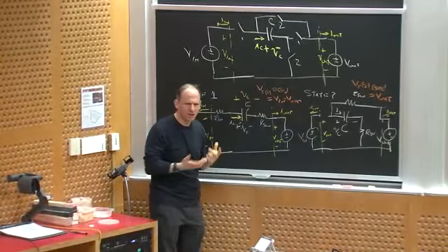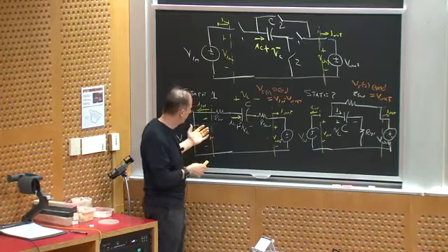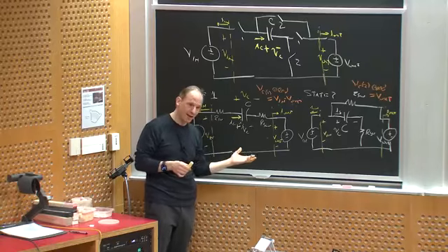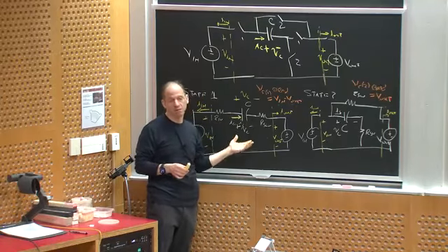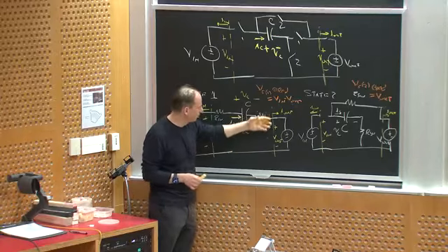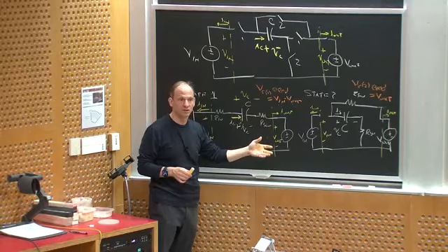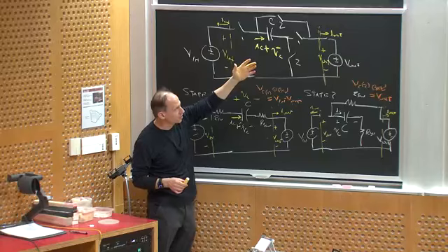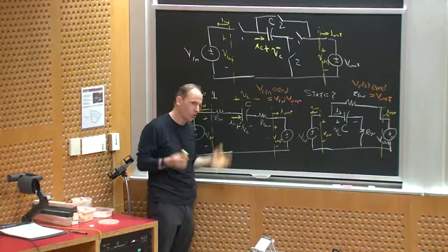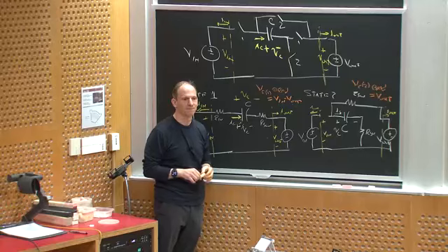The only thing you really need to know in this is where did the capacitor start in terms of its voltage and where did it end? If you know that, then you know how much charge went into it. So we have actually included the effect of the resistances. It's those RC charging things. If the resistances get small, I just make those RC charging times shorter. Okay? I see, thanks.